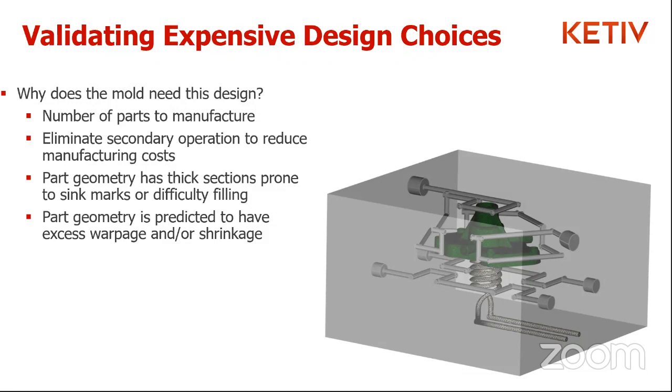Well, when you think that the part's going to have excessive shrinkage and warpage, or if it's got varying thicknesses, internal features, all that sort of thing, if you can eliminate more operations after this, if you can eliminate waste, then that's a huge win.